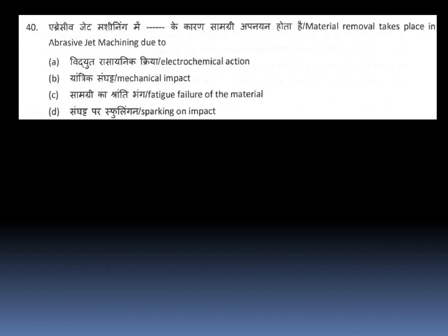Material removal takes place in abrasive jet machining due to what? Brittle fracture is here for ultrasonic machining, USM. Here in abrasive jet machining, it's mechanical impact.